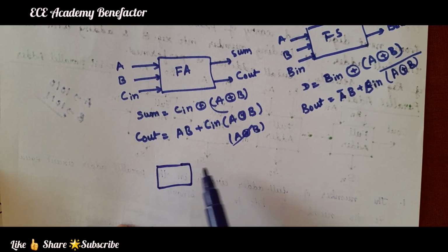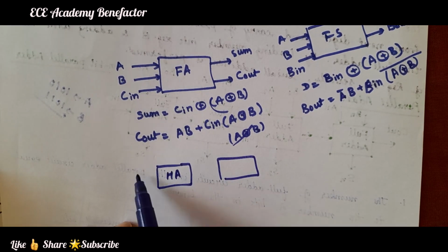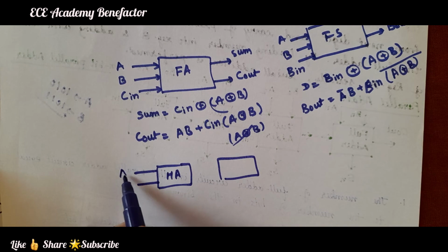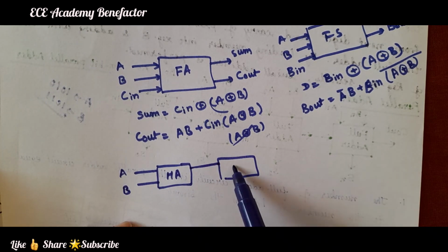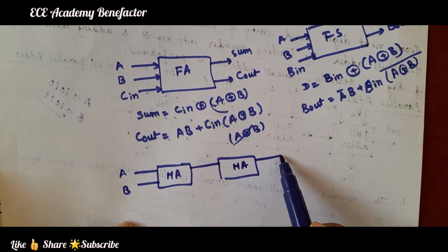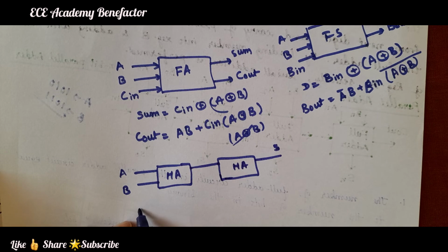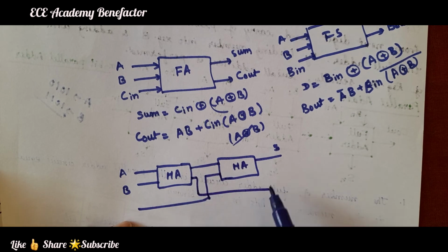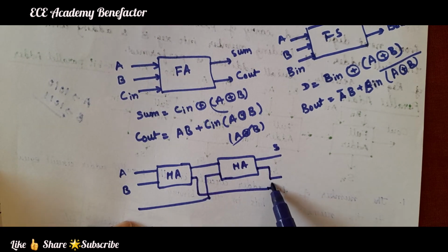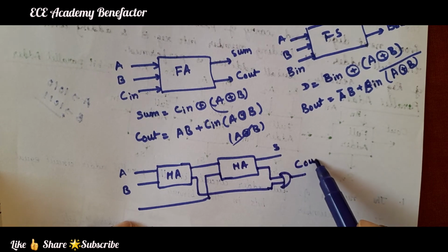Okay. And in terms of a block diagram also it is easy to remember. Two half adders. To the first adder give two inputs A and B. The first half adder's sum is going here to the second half adder to give the sum. Another input of this half adder is the third input, that is the carry input. This is the carry out, and here the carry out of the second adder, both are ORed to get the C out.